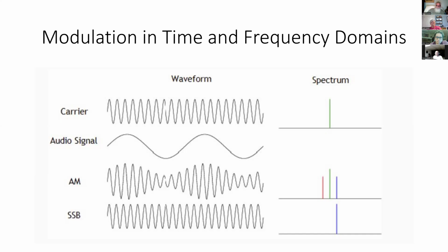And if the audio signal is just a single tone, the two sidebands would just be single frequency lines above and below the carrier in frequency. And then if we're modulating the carrier with just a tone, a single sideband signal, in this case, the upper sideband would be a constant level at a single frequency above the frequency of the carrier that's no longer there.